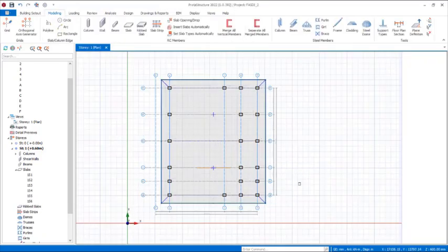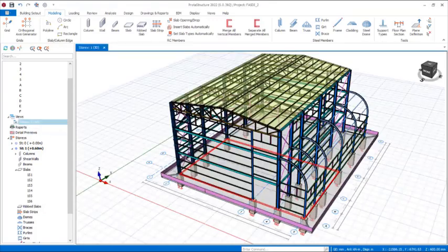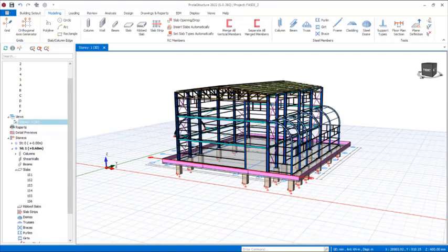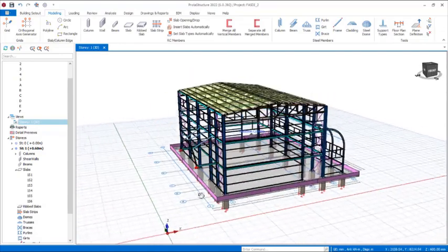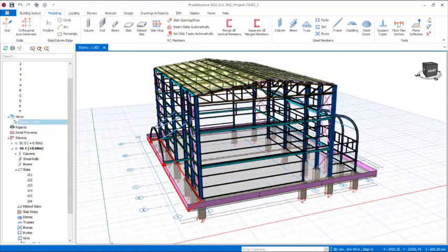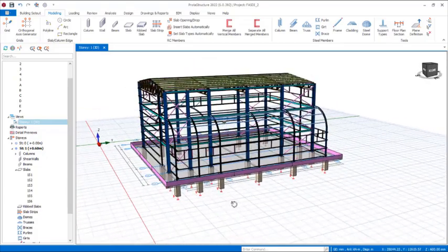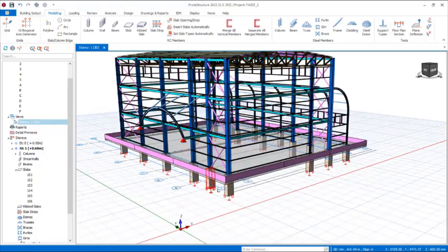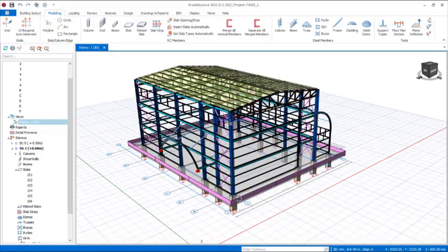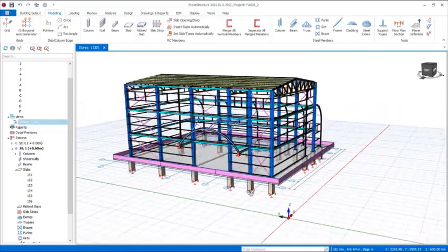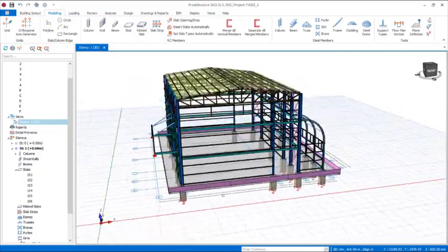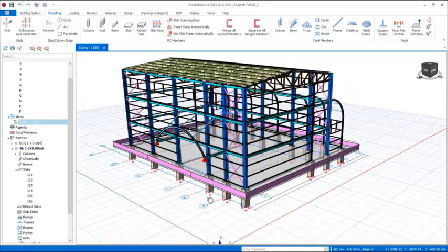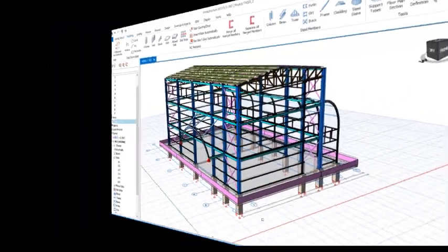All right, at this time you just go to 3D and see what you've done so far, so you have something of this kind in 3D. So this structure now is set for analysis and design, but we need to set the project parameters like the soil bearing capacities, the name of the project and the rest of that. Okay, then we'll carry out analysis and design of the structure successfully, which we are going to be doing in the next lesson, part 3.